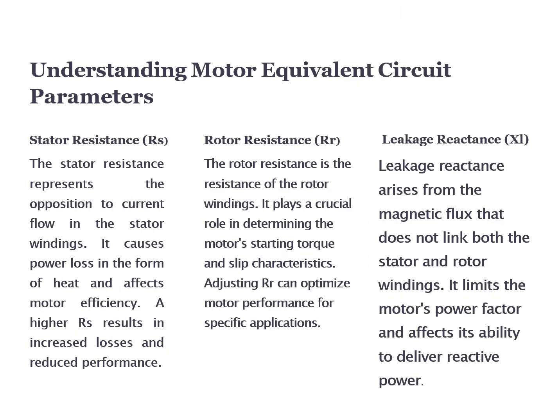Let us start with the motor equivalent circuit parameters. Every motor can be represented by an equivalent circuit, and understanding these parameters is key to analyzing and optimizing motor performance. The three main parameters we will discuss are stator resistance, rotor resistance and leakage reactance.